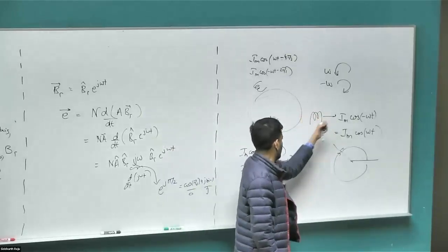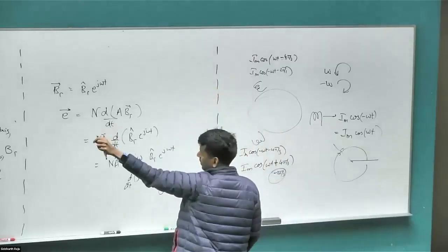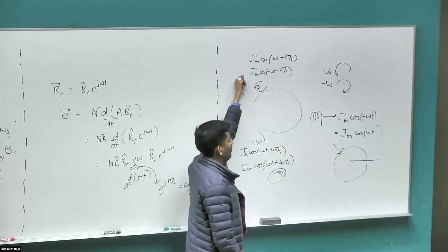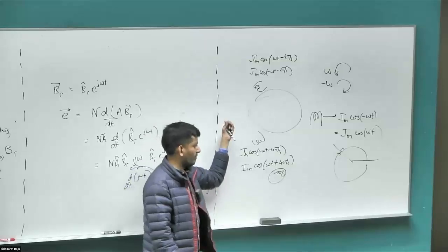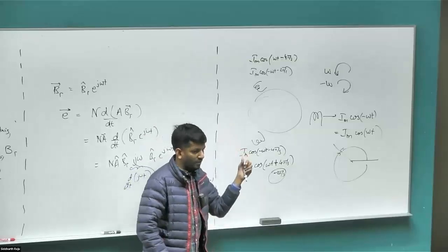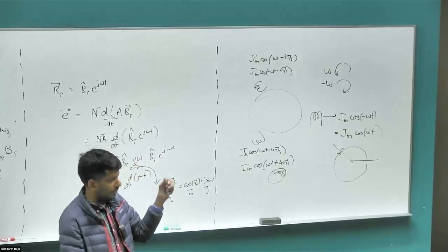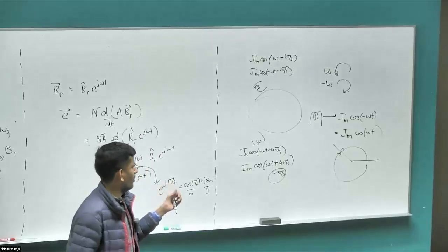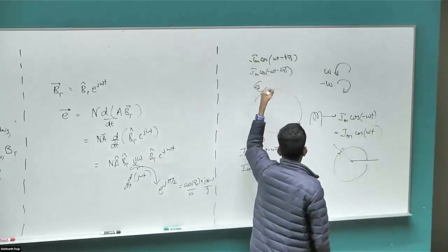What we have effectively done is we have swapped the phases of B and C phase. What was previously B, if you look at the diagram on the left, now became C, and what was previously C now became phase B. So when you swap the phases, we know that if you do a single swap, then the motor would rotate in the opposite direction. If you do a double swap, it goes back to the original rotational direction. That's all it means.